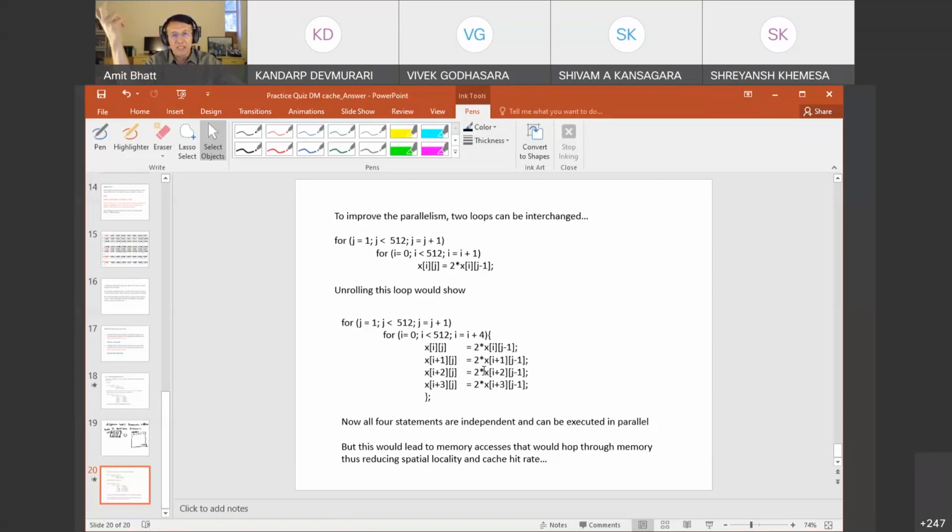One is the superscalar processor, where you have multiple instructions. So there are several execution units, and those execution units can work in parallel. So a number of instructions can go in parallel. There might be, say, 2 or 3 ALUs. Then 3 multiplication instructions can go in parallel, and then execution may be faster.